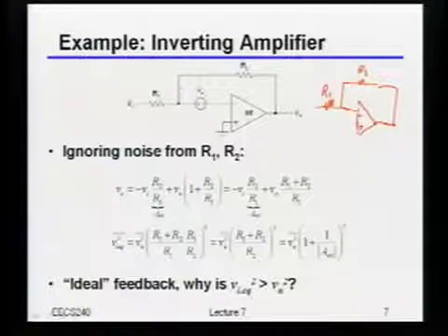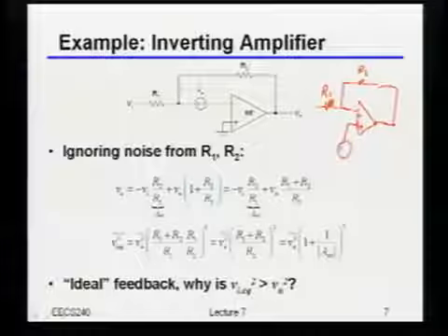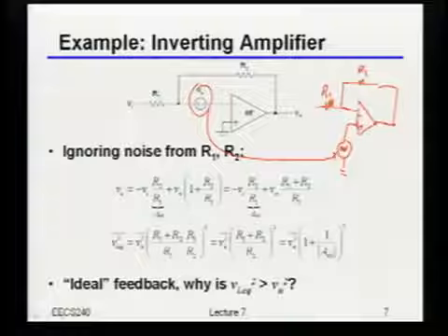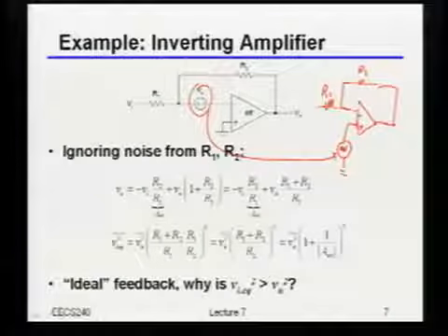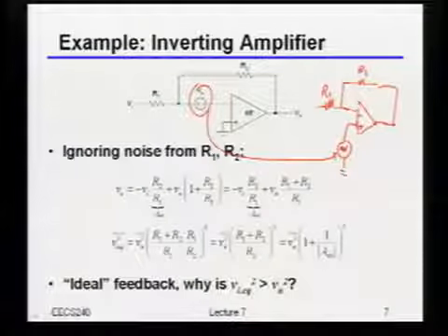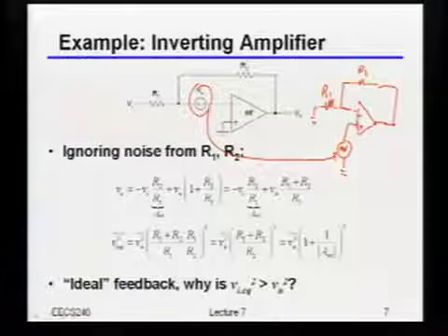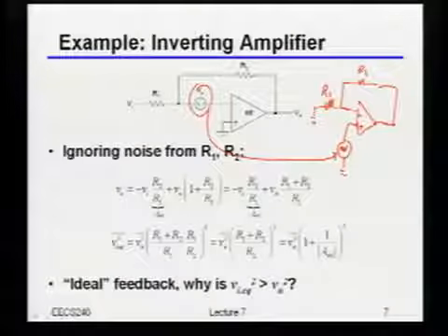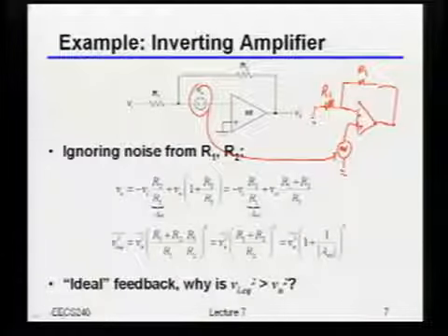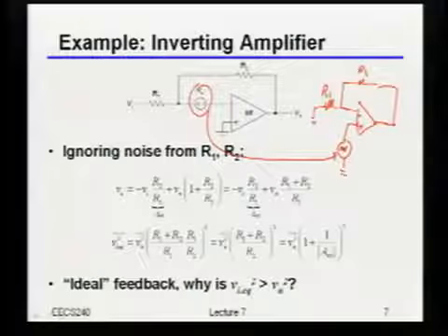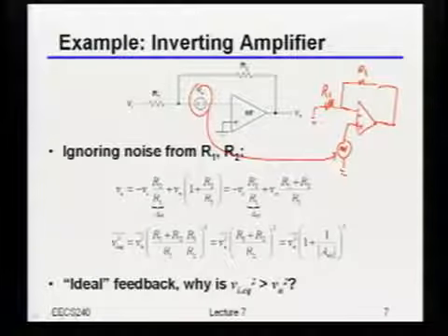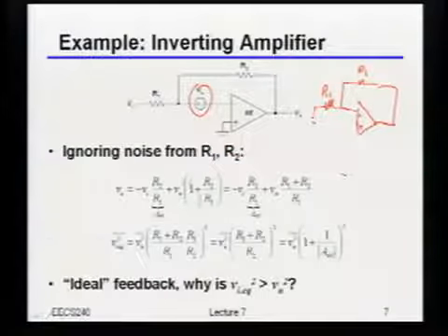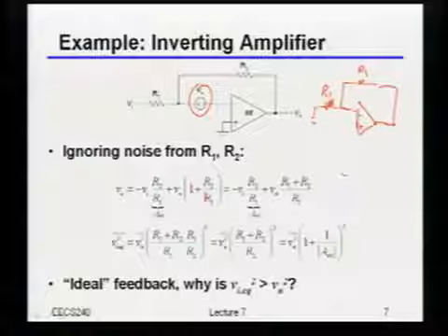Well, if I'm okay with doing that, then I can take this voltage noise over there and basically put it down at the bottom, right? Just tie it onto the other input of the op amp. So now it should be pretty clear, I just have that non-inverting configuration, right? Make sense to everybody here? Okay. So once I've done that, you can pretty quickly show the gain there is this 1 plus R2 over R1.